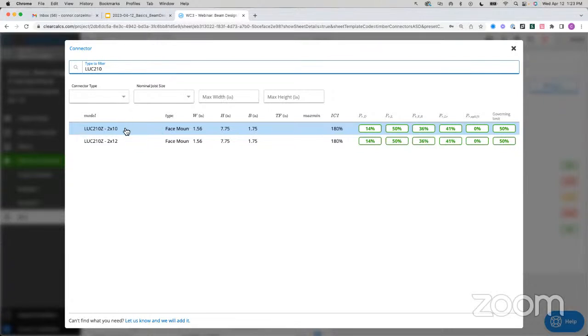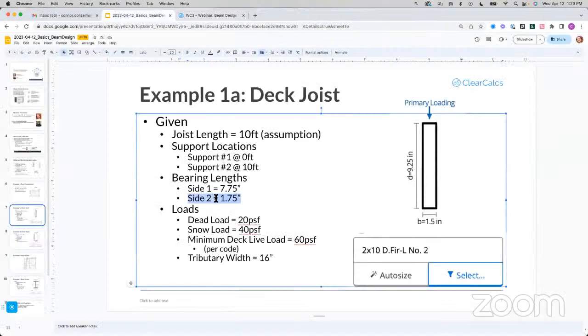All right. So we can see at the top, we've got this 2x10. As we spoke at the beginning, our joist was a 2x10 selection. So this is likely what's being spec'd. And we could see our width here is 1.75. So that's where I got the 1.75 in this calculation. So we'll go ahead and do the loads, or the next calculation. Sorry, I lost my train of thought there for a second. I love Vicus's laughing emoji there.